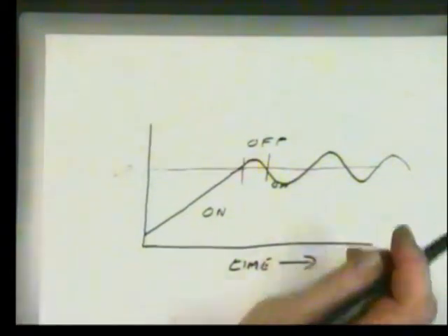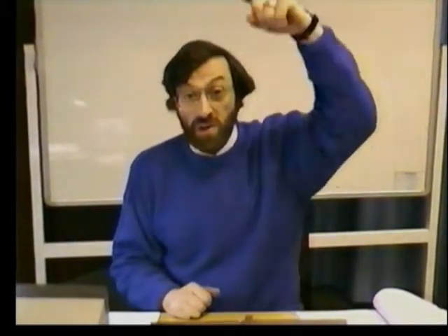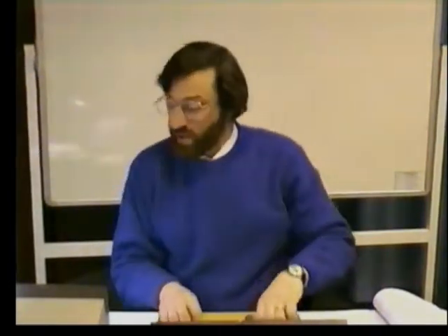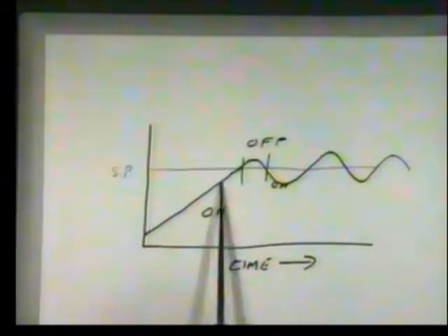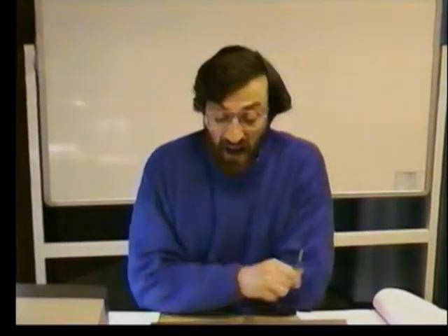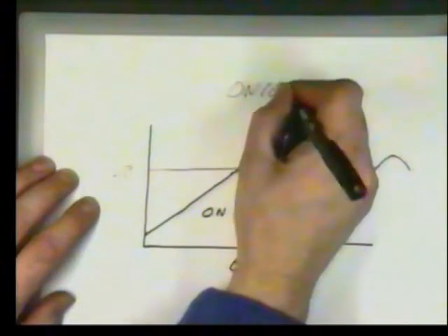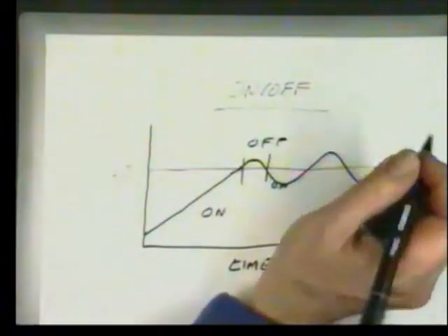And that's true for any unidirectional system. A heater that is heating a room or air conditioning that's cooling it. You've either got it on or off. So what will happen is you'll rise to your set point and then you'll start switching between the two states, hopefully gliding along the set point. What you want is nice slow oscillations. This is a valid control technique. It is called on-off control.